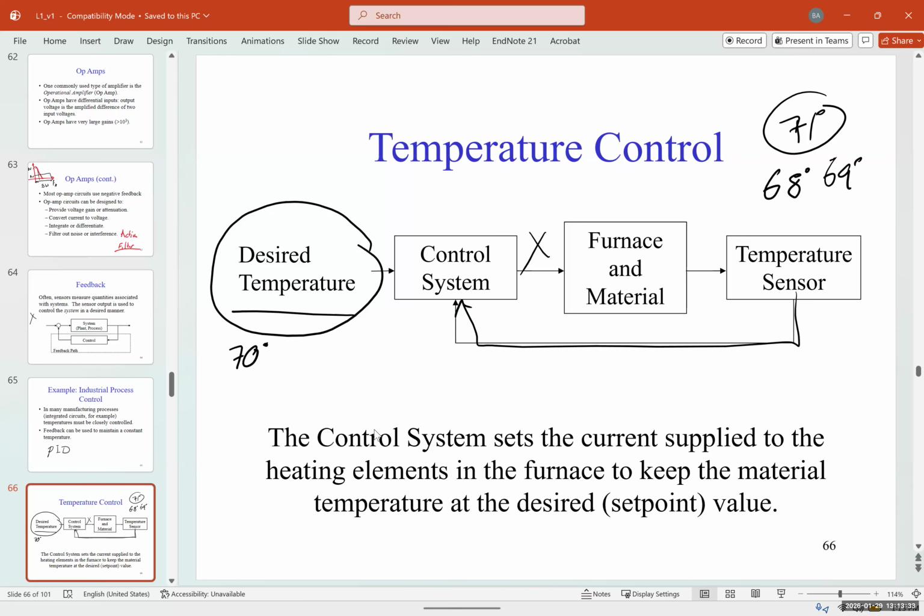So the best way is you put multiple temperature sensors and you get an average of that, and then you decide to turn on the furnace or not based on that. And the newest thermostats have multiple sensors. One is usually on the thermostat, and one is furthest from the furnace itself. They could communicate wirelessly or with wire, but usually they do it wirelessly on Wi-Fi or Bluetooth. And we have what we call a mesh network. And then the control system can decide based on that.